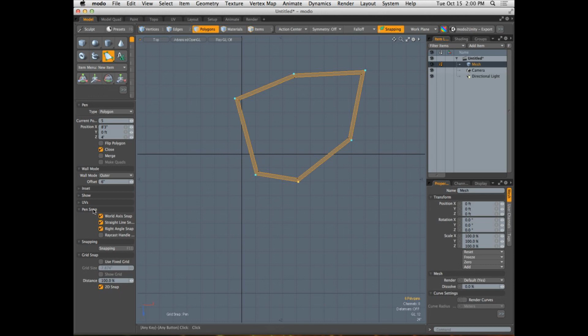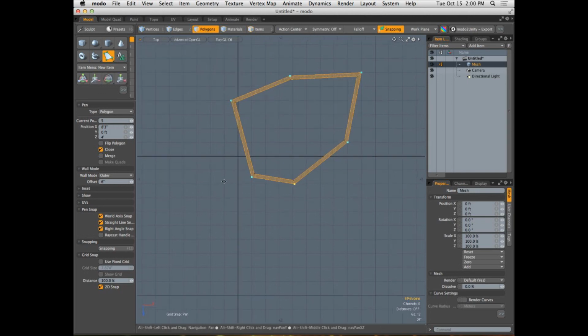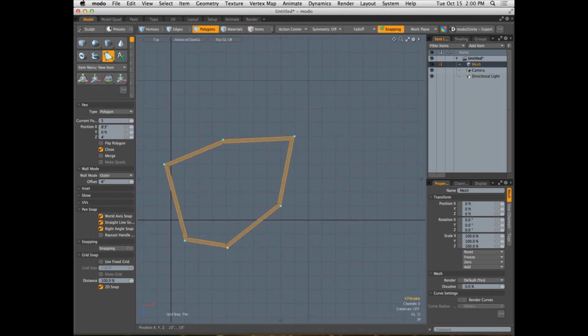and you can see that those three options have become ungrayed and now they're being applied within our scene. These three options allow us to achieve that level of accuracy that we're really going for. Each one of them is going to allow us to snap our control vertices to a whole series of different elements within the scene. So we have the world axis snap. This is kind of like the grid snap. It's going to snap to all of our local axes.